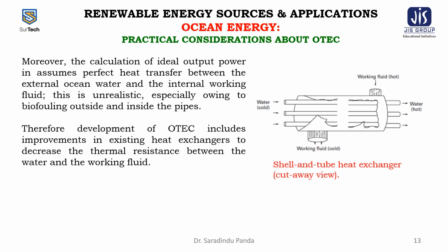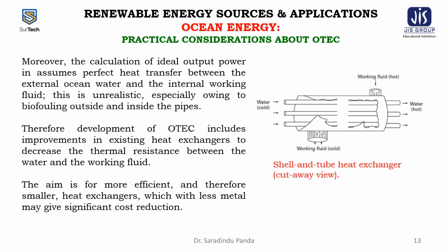Therefore, the development of the OTEC includes improvements in existing heat exchangers to reduce the thermal resistance between the water and the working fluid. The aim is for more efficient and therefore smaller heat exchangers which, with less metal, may give significant cost reduction.